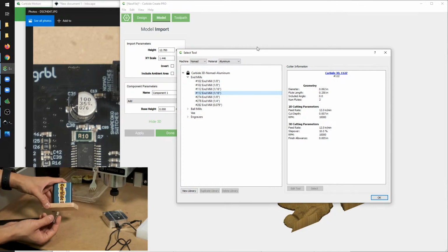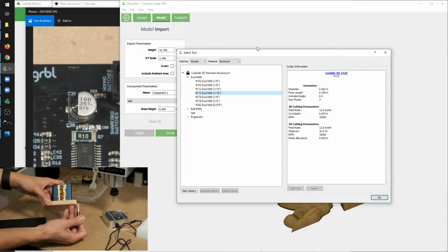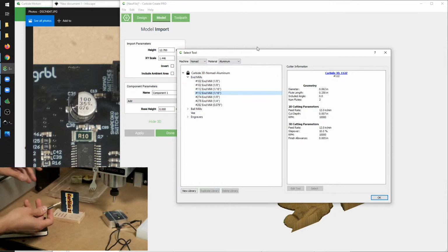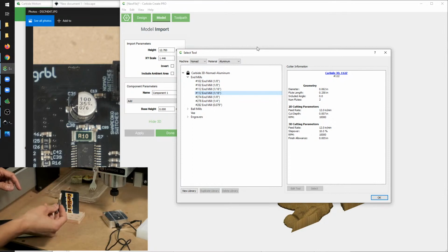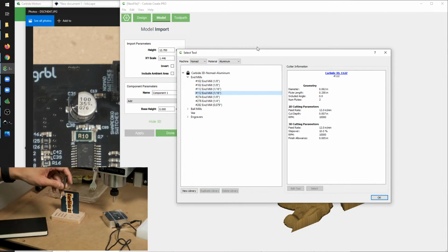It's not good. So the criteria for is a material practically machinable on a CNC is, can you feed the tool fast enough so that every revolution of the cutter, the end mill is taking a reasonable sized bite out of the material. In steel, you can actually get that reasonable chip load or bite of the end mill into the material, but it comes at the expense of depth of cut, because the deeper you cut, the more material you're excavating with every revolution of the cutter. For steel, that limit that the Nomad can handle is extremely low.